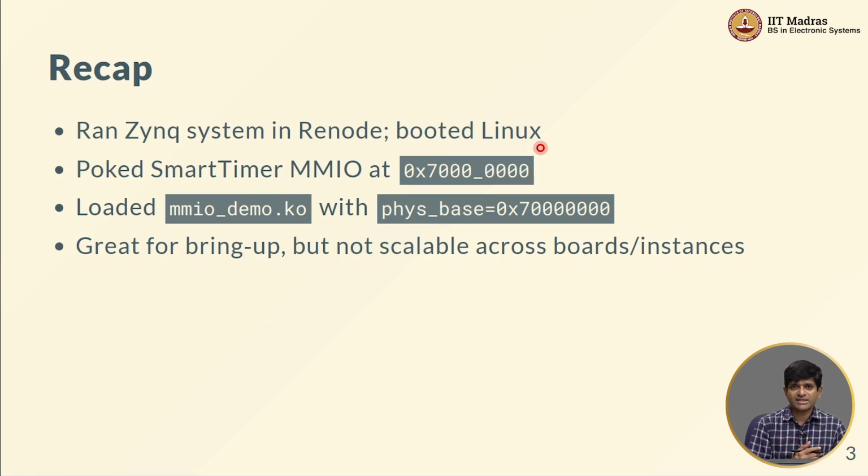But you might have noticed that especially in the second demonstration where we booted something corresponding to the Zynq Z board, I mentioned that there is something called the DTB that needs to get loaded in a specific place. Otherwise, the system boots up, the problem is you don't see any messages as it boots up. That's an important distinction to keep in mind. The system is actually booting, it's working fine. It's just that it doesn't know where the UART is connected, and therefore is unable to output messages in such a way that you can actually see them.